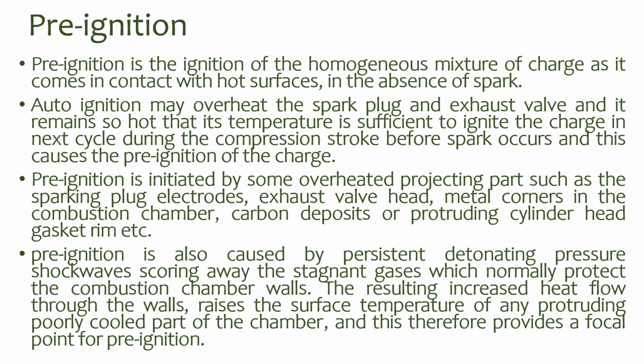Pre-ignition is also caused by persistent detonating pressure shock waves scouring away the stagnant gases which normally protect the combustion chamber walls. The resulting increased heat flow through the walls raises the surface temperature of any protruding, poorly cooled part in the chamber, and this therefore provides the focal point for pre-ignition.